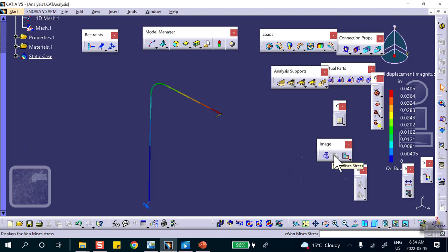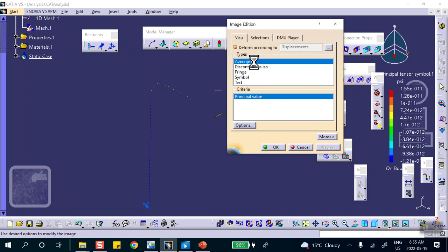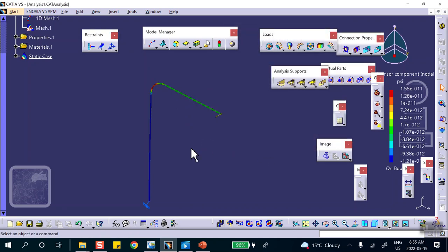You can plot the principal stress, but unfortunately, the principal stress they give you is the axial stress, which is useless. Usually when you do bending, we are not that interested in the axial stress. You can do principal stresses. This is it, right where your deflection is. But look, what are you getting? I mean, the color looks okay. First of all, they're like that. But what are the values?